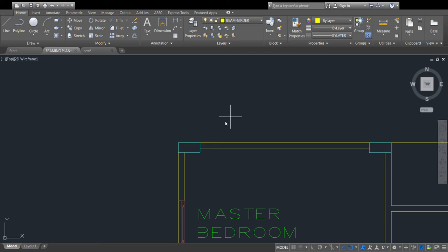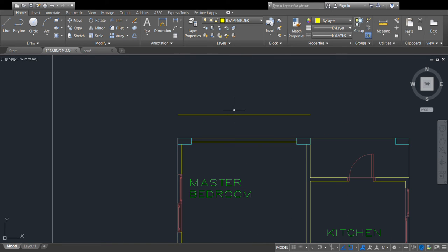But if you're going to use a scale, multiply it by the scale factor. Now, the very first dimension must be 15 mm. So if you're going to compute that, that would be 600. So press any of the lines, the aftermost line, and then the next line, offset it, then 400.